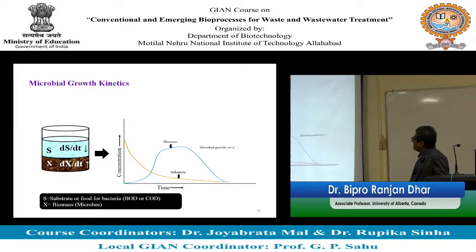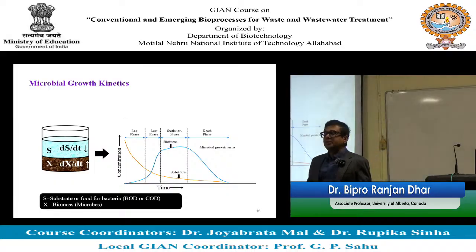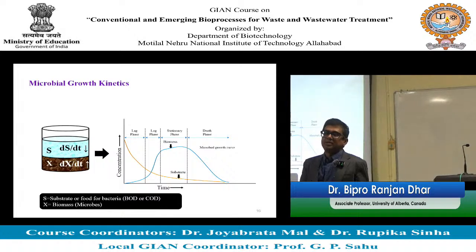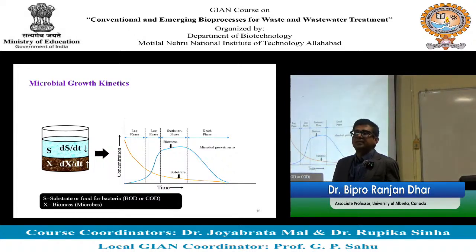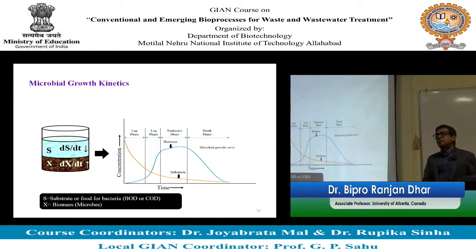On the other hand, for biomass concentration, initially there could be a lag phase, because microbes need some time to adapt to the substrate before they can start utilizing it. Depending on what kind of substrate you are providing, it could be hours, it could be minutes, we don't know. After the lag phase, microbes are going to grow exponentially, because they started utilizing the substrate, and after a certain period of time they are going to reach a plateau.